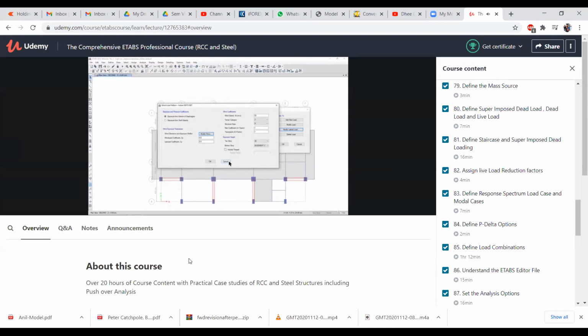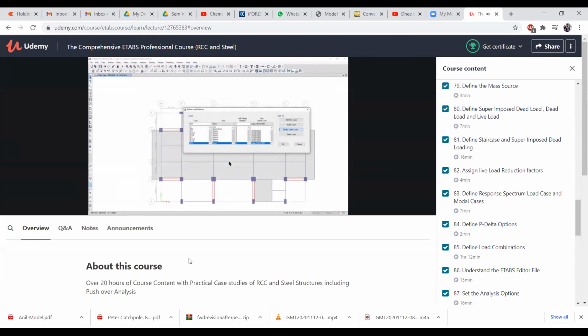So what we can do is have full control of the loads that will be applied on our model. Because if we are talking about a 100-meter building or a 200-meter building, wind load is always dominating in one or other part of the structure. So what we need to do here is left click here and then select auto lateral loads as user loads and then click on modify loads.